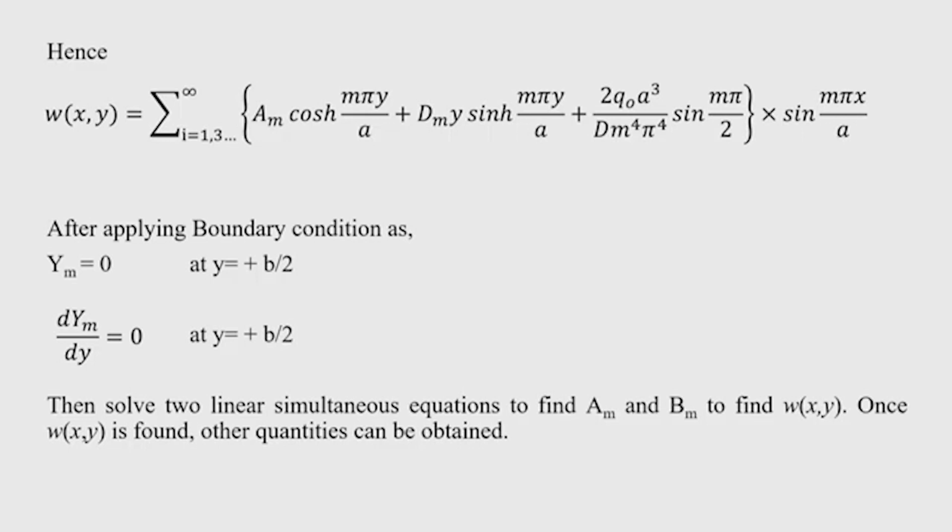I have illustrated the systematic method known as Cramer's rule, that you can use by expanding the determinant that I have shown, and then you can obtain the constants a m and d m completely. When you obtain a m and d m, your problem is solved, that means the deflection series is completely known. After obtaining the deflection you can explore other quantities. That means, if you want, say, bending moment or shear force, you can derive it from the deflected quantities.